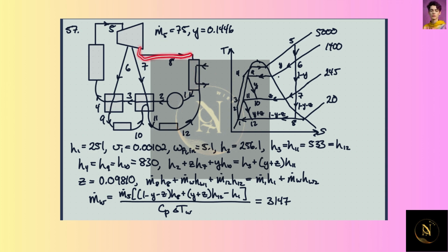We have the output from the turbine coming in, and then we also have the output from the steam traps coming into it. Then we have it coming out to the pump, going through two closed feedwater heaters, heating it up some, and then heating it up again. The heat exchange from those closed feedwater heaters comes from two taps, two pressure bleeds in our turbine, at two different points.